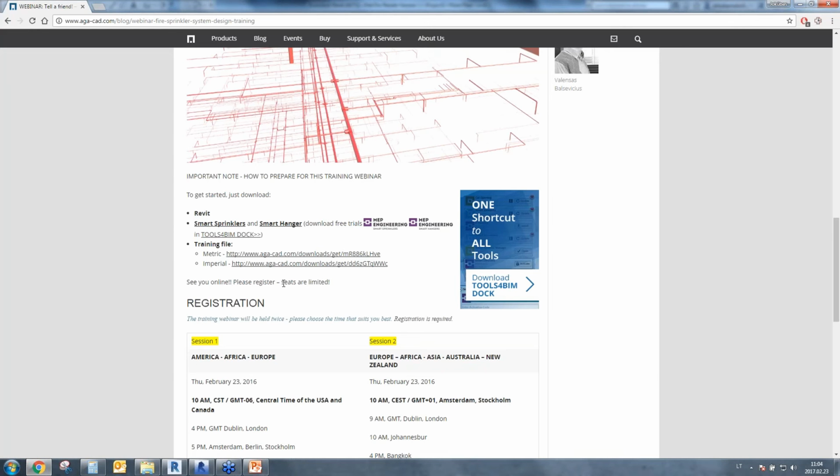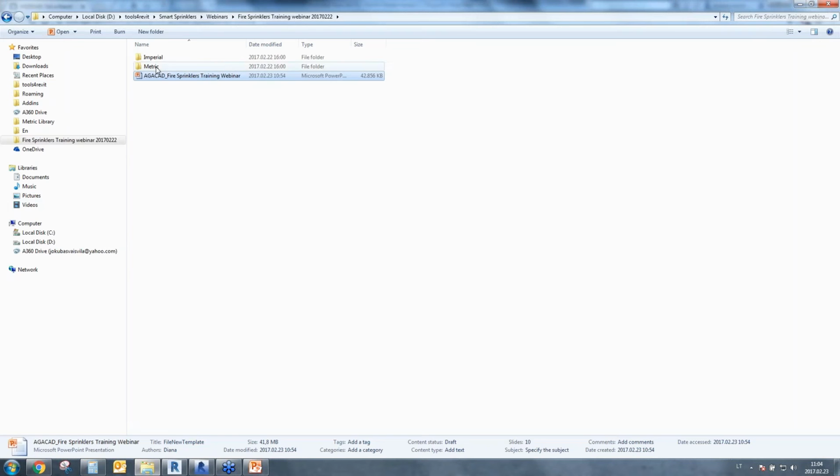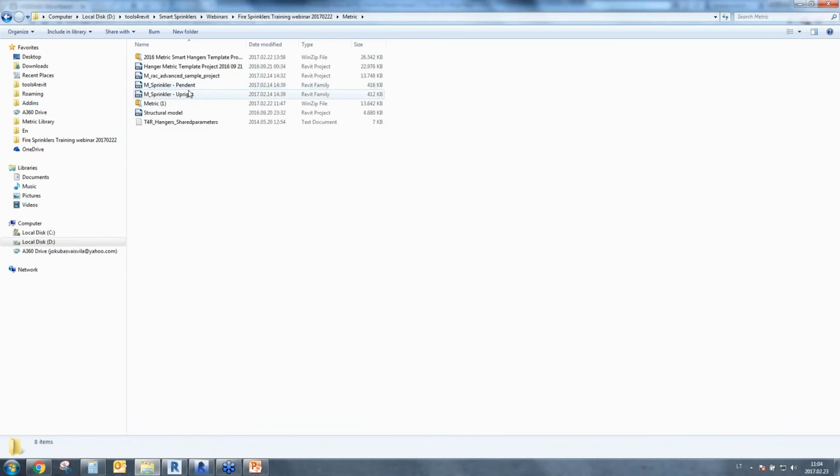Before the webinar, you got some information on how to prepare for the training. As usual, you have to have Revit and those 2 different softwares that I mentioned before, smart sprinklers and smart hangers. As well, you have to download the metric or imperial training files. What is included in those files? It includes 3 different files. One is the project file, and 2 of them are just sprinkler families.